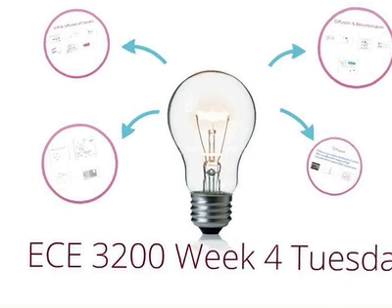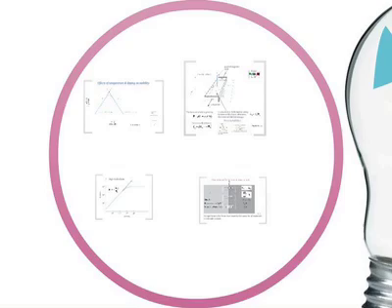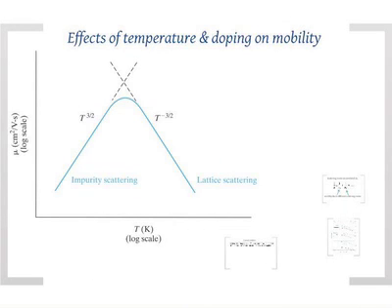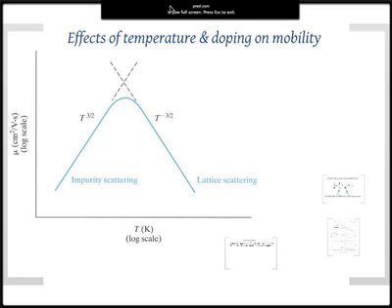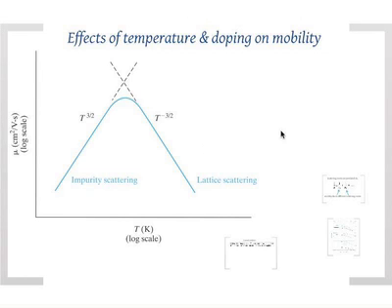We're going to start where we stopped last time, which had to do with scattering. We were still talking about mobility, so this still deals with the drift current. You apply voltage, the electron moves. What is the velocity as a function of the applied electric field? It is described by mobility, mu. Remember the units are centimeters squared per volt second. And this is plotted in log scale.